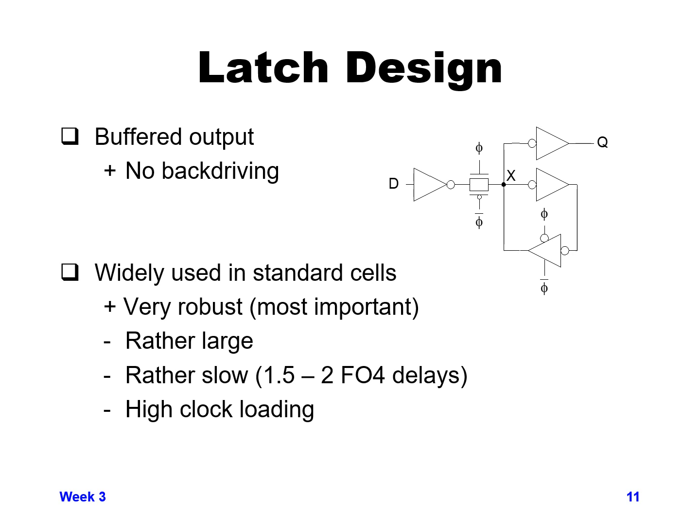If you go back and look at the previous foil, you can see that when we had our inverter that drives the tri-state, when we took our output at that inverter, between the inverter output and the tri-state input, since that's driving out to potentially multiple receivers, if you had any noise on that, that could potentially go through the tri-state and interfere with your state node. So this does not have that problem in its design.